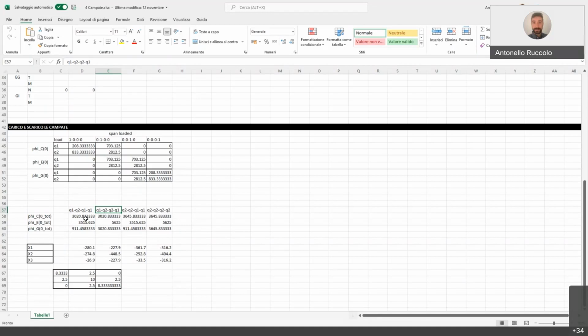In this case, we have to consider the minimum load Q1. And varying the load conditions, we can also have higher values of static unknowns in the first and the last internal span. Similarly, we will find different values of the maximum bending moment in the span.